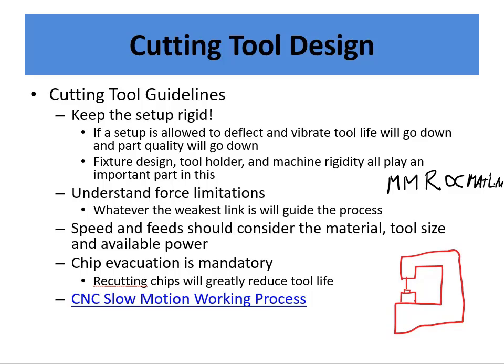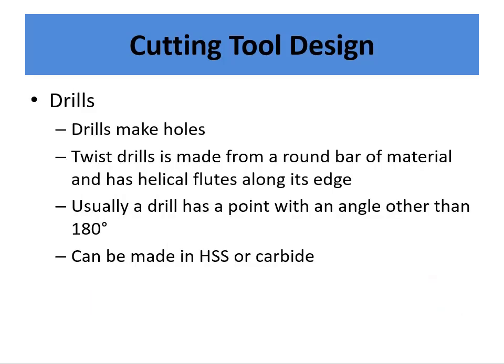Okay. So then we just have a couple details of some tools. So drills. Drills make holes. It might seem pretty straightforward, like, oh, okay, yeah, drills, sure, they make holes. You can have an entire career just designing drills. There's a lot that goes into drills. But for now, we're going to go over this in the course of doing all kinds of tool design. But drills make holes, and generally when we talk about drills, we're talking about twist drills. So it has helical flutes along its edge, and those flutes are designed usually to just get material out of the way. So they kind of auger the chips out.